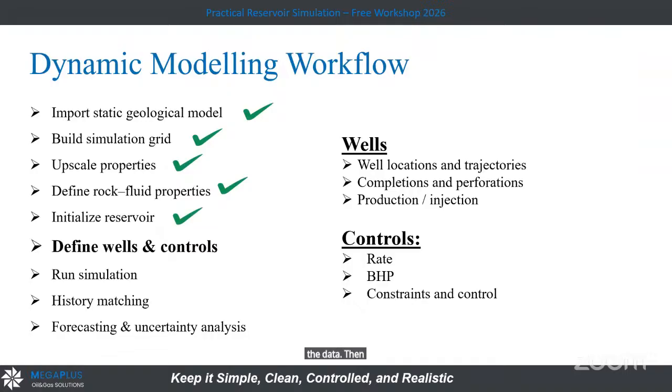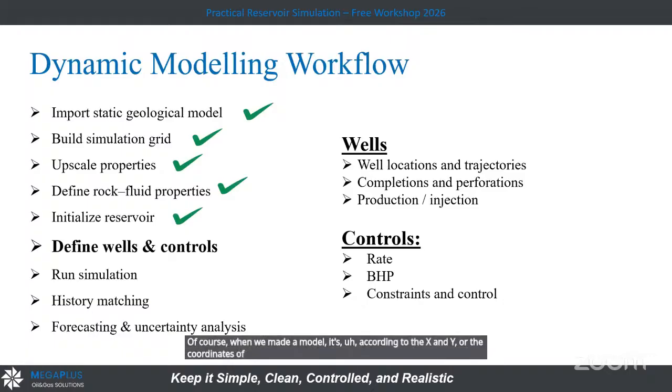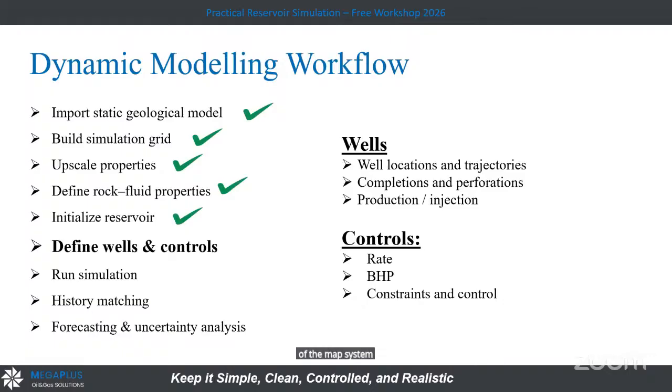Then in the dynamic model, after making this initialization, we have to define the wells and control. The wells drilled in the field, of course, when we made a model, it's according to the X and Y, or the coordinates of the map system. So you have the X and Y in your model. You have to insert all the well models in the right location, and then something called control.